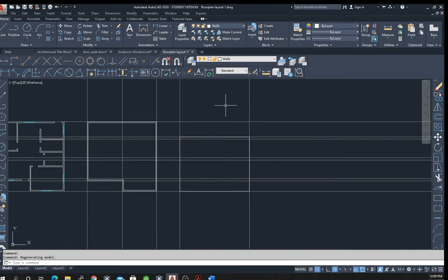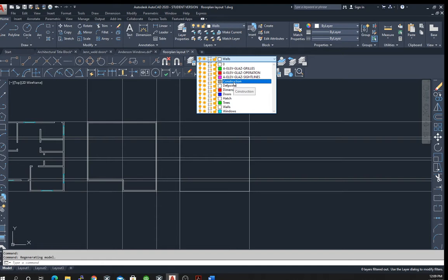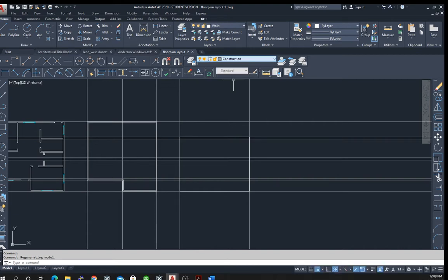Now, we need to add one other construction line, right? We need to add this other one for the 15.3 feet in from this line. So let's go ahead and do that. Or alternatively, we could not do that. Let's add it in anyway. We can do that with offset. So a construction line, offset, 15 feet, 3 inches from this line, and we move inward, or move towards the right, and we hit enter.